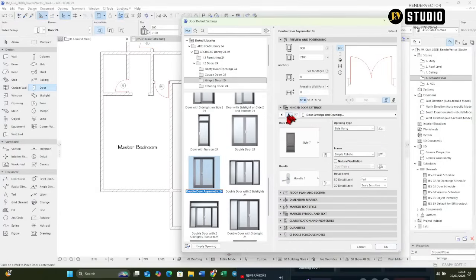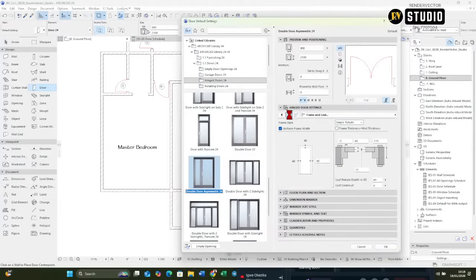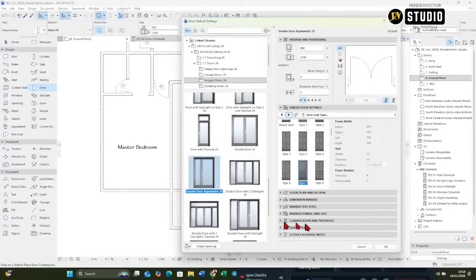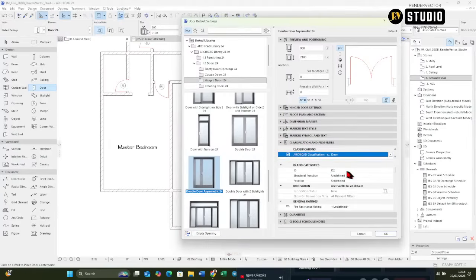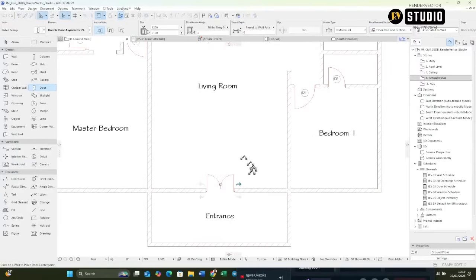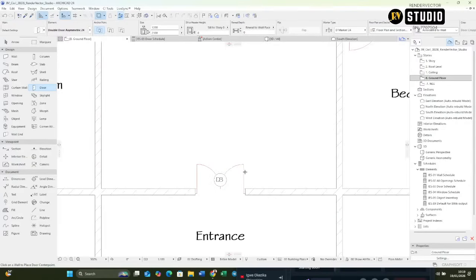So now when I'm done, I'll just move to the right. No, I'll first drop it. Before I drop it, I'll make sure I set the classification to D3 because it's a different door now. D3. It can't be 900. It has to be 1200. Alright, okay. Now D3, 1200 asymmetric door. Let's see how it's going to be in the entrance. So nice. That's our D3.